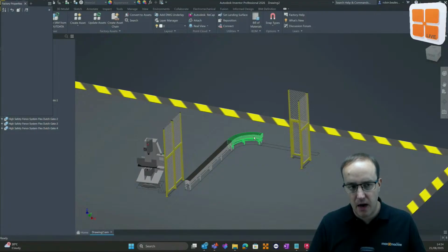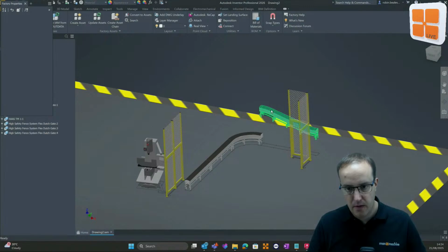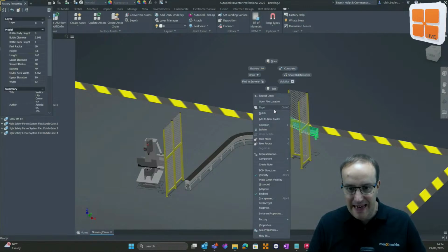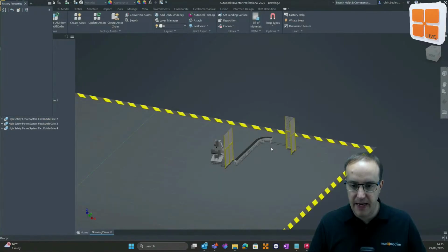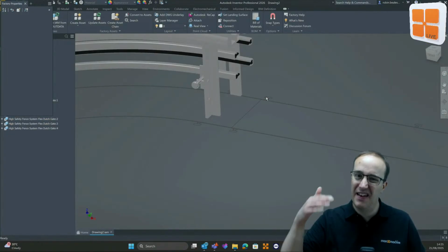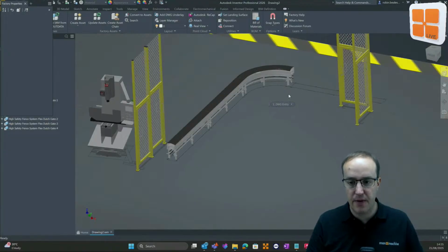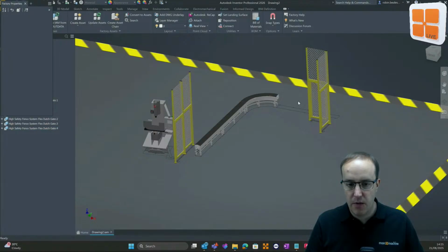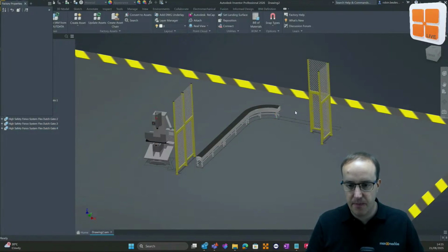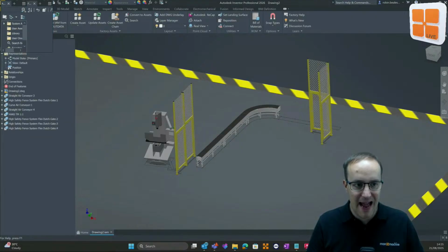And you'll notice that underneath my 3D assets in Inventor, I have the AutoCAD 2D that still exists. So it's underlaid so that I can see what effect something has on the 2D flow. So I've deleted that conveyor here. And then what I'm going to do is show you that I can add components here directly inside of Inventor.